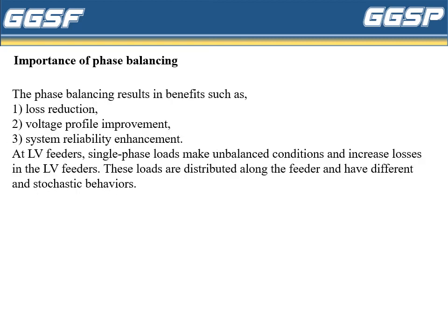Then what is the importance of the phase balancing? The phase balancing results in benefits such as loss reduction, voltage profile improvement, and system reliability enhancement, and many more. At LV feeders, the single phase loads make the unbalanced conditions and increase losses at the LV feeders. These loads are distributed along the feeder and have different and stochastic behaviors.